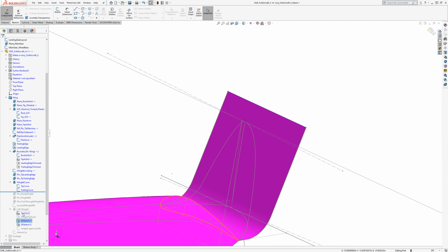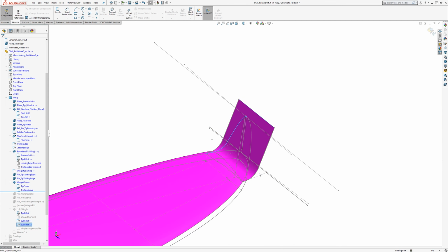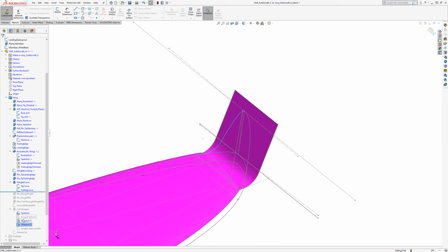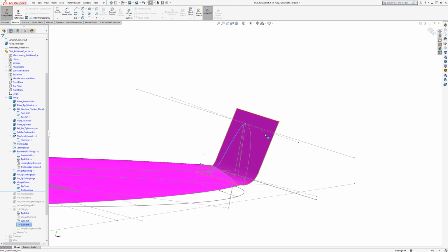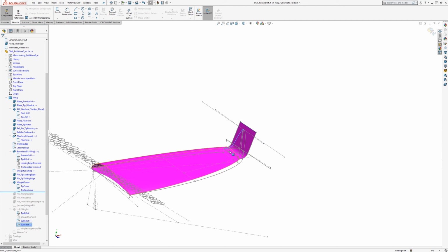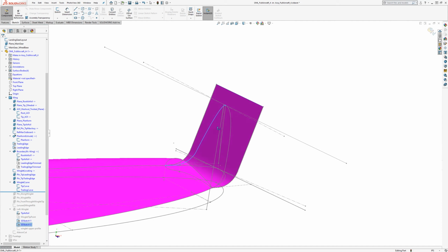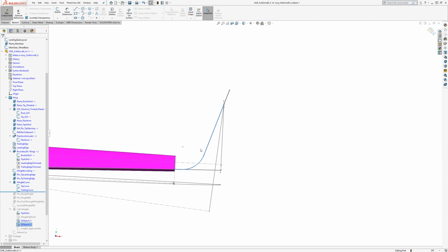So we have the tip airfoil, and these again are pretty much the same concept as the leading and trailing edges before, but they're intersecting between the planform and this surface. This sort of takes the place of that twisting dihedral plane for the winglet. It's a slightly twisting, curved plane.